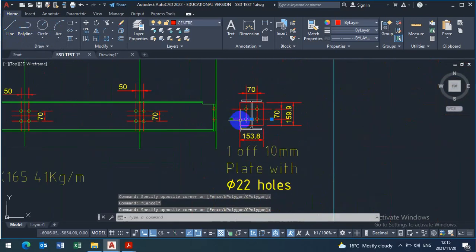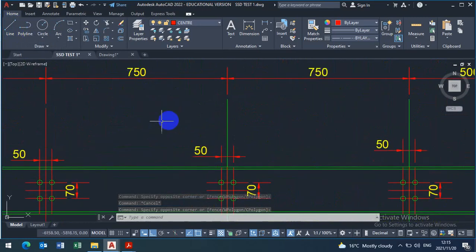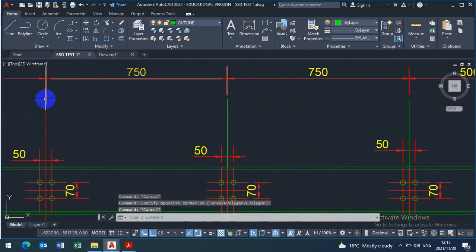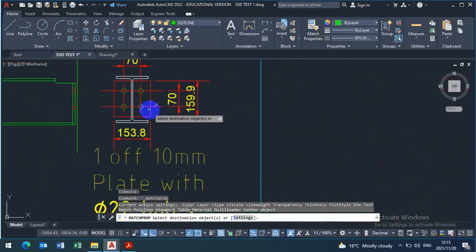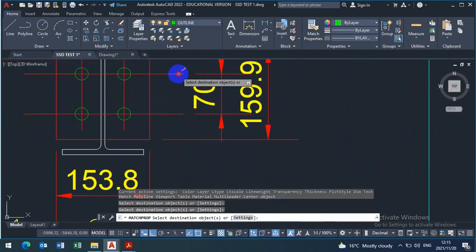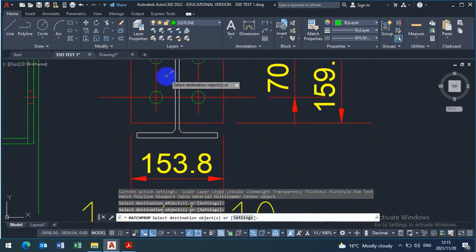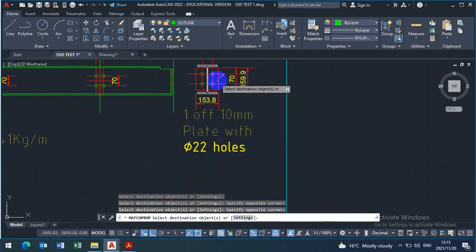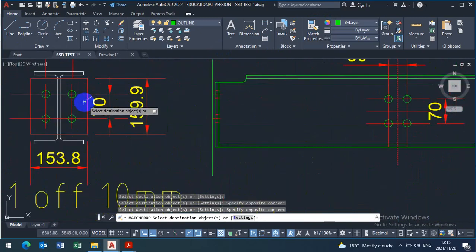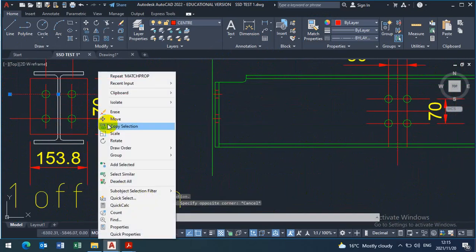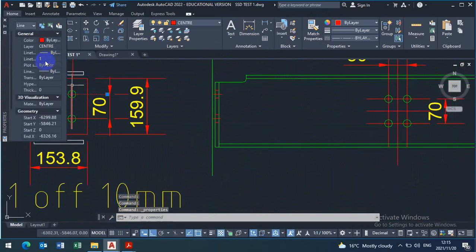So if you see that it's still not accepting, you need to look for some center line. Yeah, for a center line that is like this one, then you match from here. So you select this center line, match properties to the other ones. Yeah, it's still center, so we need to reduce the dimension, the distance in between. 5 maybe is too much. Enter. Let's see on what scale it is on. Select, right click, properties, try to say 0.5, enter.